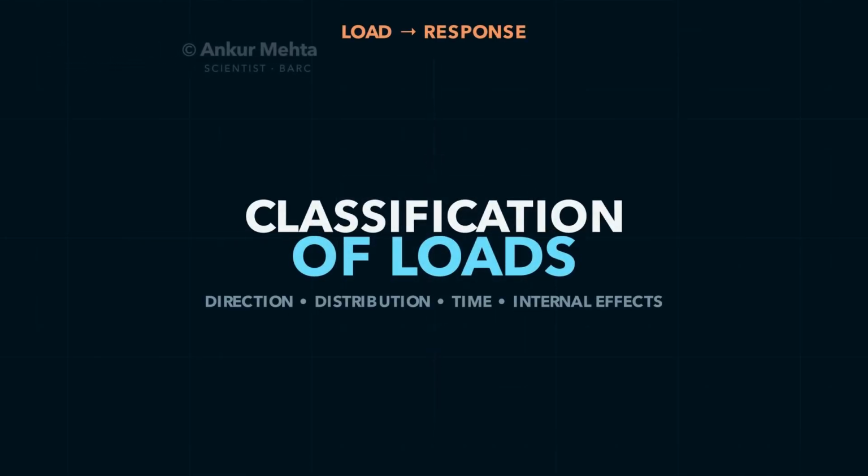Every structure begins with a simple question: what is pushing, pulling, twisting, or accelerating it? Before calculating stress or deformation, an engineer must identify the load correctly. In this lesson, we will classify loads by direction, spatial distribution, variation with time, and rate of application, then connect each classification to the internal forces it creates.